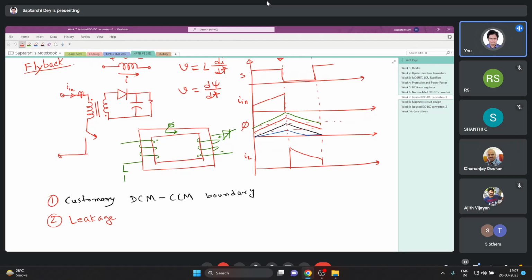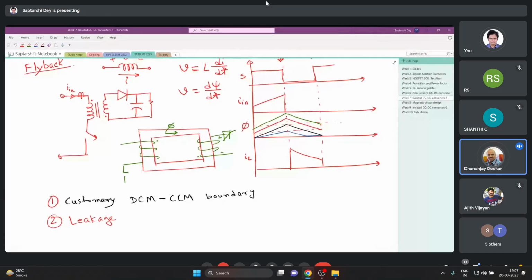But where we are going with this discussion is not exactly my point. Okay, that is fine. But here in magnetics, it is a coupled inductor. It has to be defined with the help of leakage, with the air gap introduced in the path length of that flux. How to define the air gap, the slope of the BH curve, in what degree it has to be there.